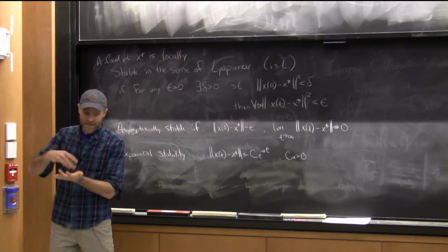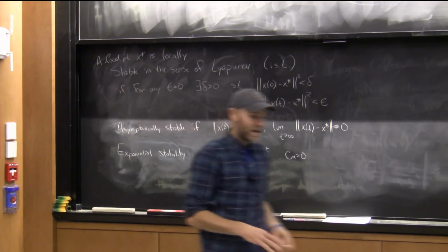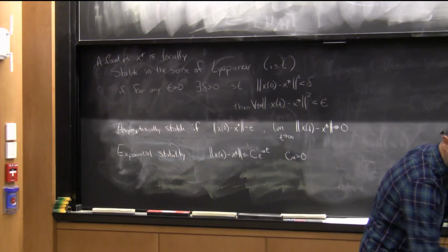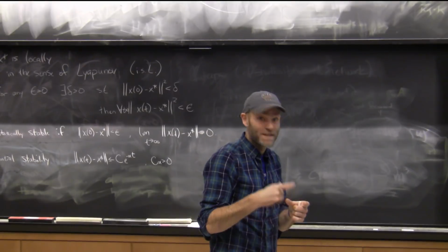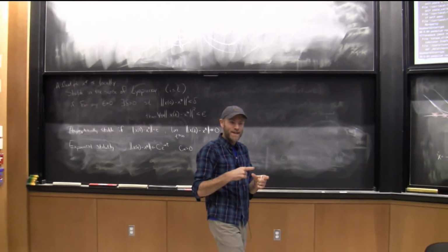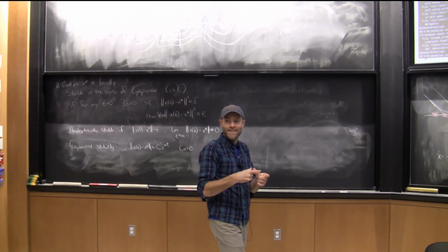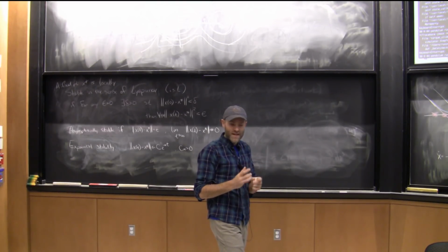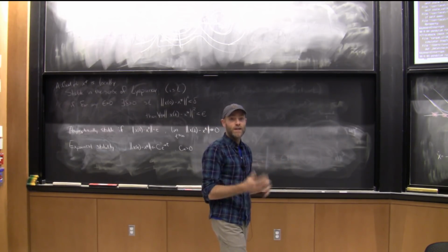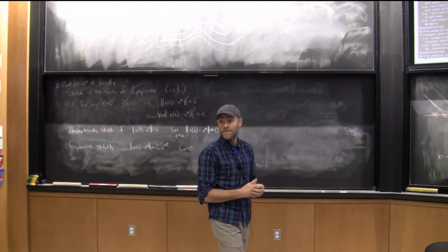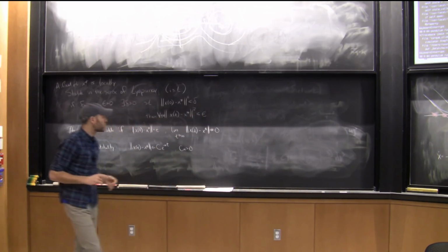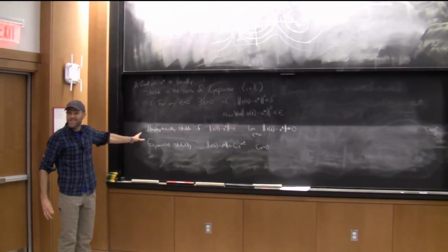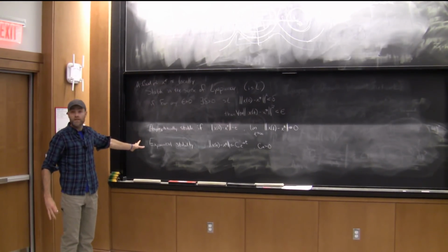If I wanted to throw a box and have it land exactly at a point, for instance, if it landed right next to the point, nothing's going to sort of nudge it over, but it'll sit there forever. So if you ask it to be exponentially converging or even asymptotically converging, then you're going to fail. And it turns out that matters if you're picking up things with your hands. Anytime you have contact or frictional contact, you end up having to go to stable in the sense of Lyapunov, and typically not asymptotic stability. Is that clear? Feel free to ask if it's not.